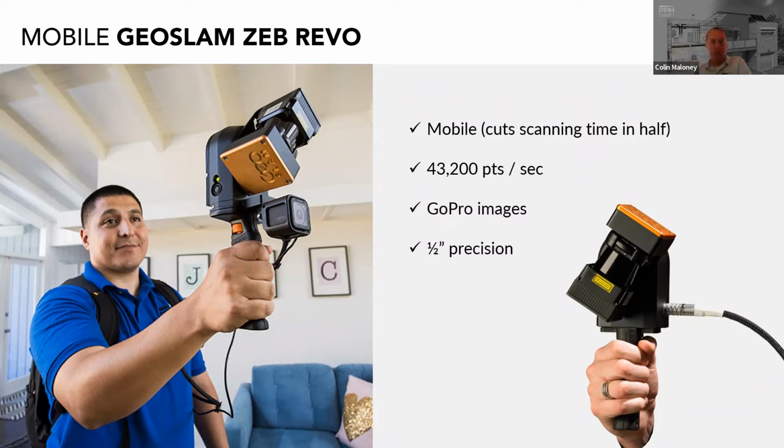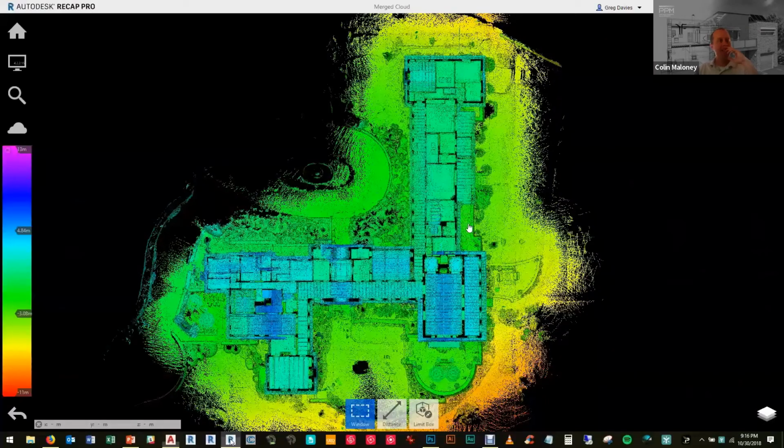So next, we're going to watch a short video displaying the output from a scanner like the one you see here. And that last check mark there, I want to mention that GeoSlam has produced scanners that get closer to a 1/16 of an inch precision in the cloud itself. So with that Revo that you see in that photo, that was a reliable amount. But again, the construction quality will make your point cloud vary in other ways as well. So yeah, let's watch this video.